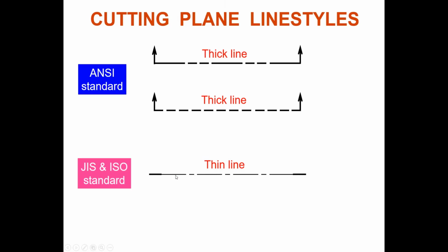You have 3 pencils, so which pencil do you use? Class, are you listening? Which pencil for your cutting plane? 4H? No, 4H is the lightest one. I'm talking about the middle one, HB, okay? Remember, center line and hidden line are HB, right, guys? Are you listening or not? Class, your orthographic. Not 4H, guys. 4H is for all your extension lines and construction lines. Clear, class?